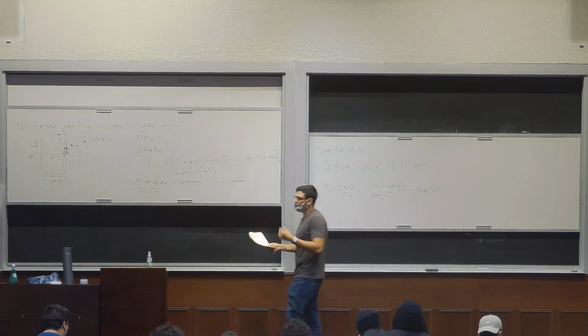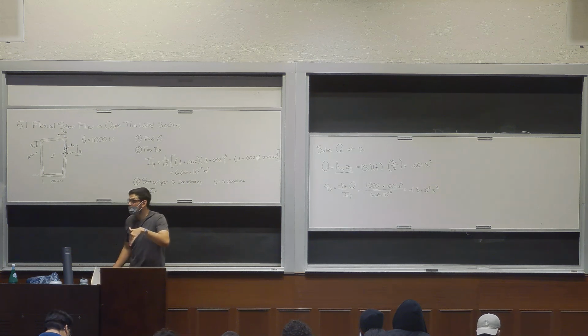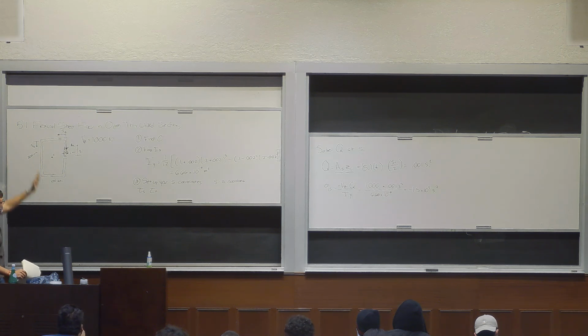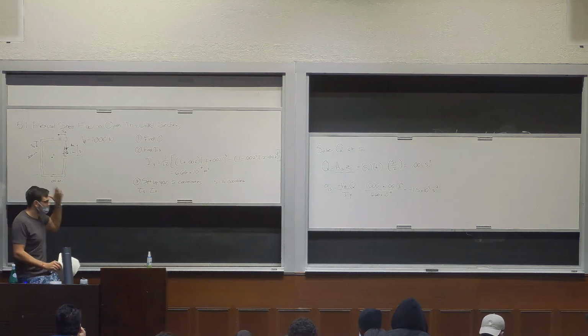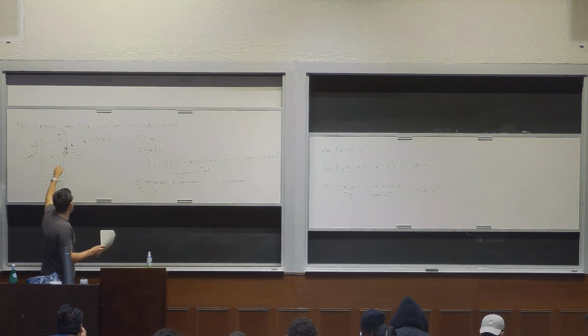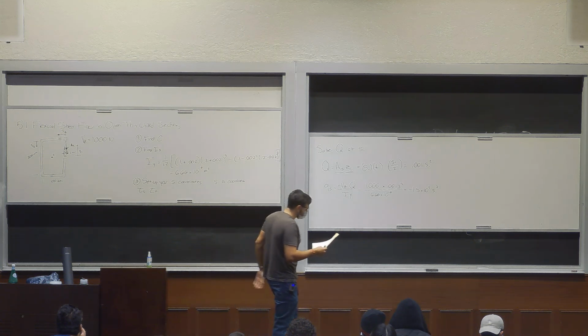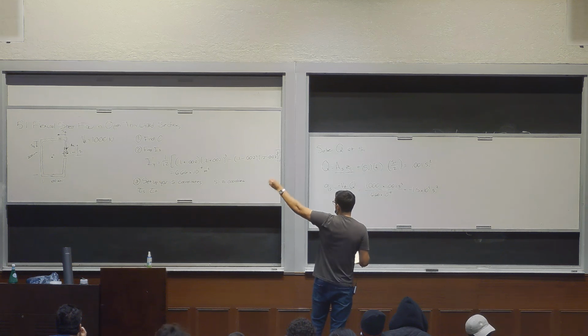What you'll notice for these problems is that if you have a shear force acting in the same direction as the length of whatever structure you're looking at, if V_Z is acting vertical, and you're looking at a vertical portion of one of these structures, the distribution is going to be parabolic. If it's perpendicular, for example here, it's going to be linear. Parabolic, linear, parabolic. That's a quick thing to check your answers. If you get something linear here, then you're doing something wrong. So we have q_s, and now we know how it's distributed along that portion.